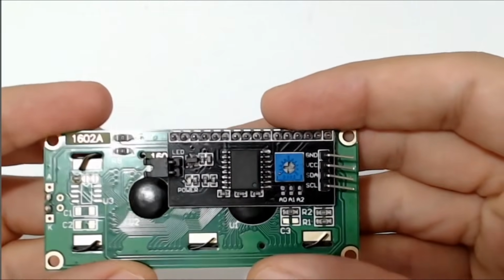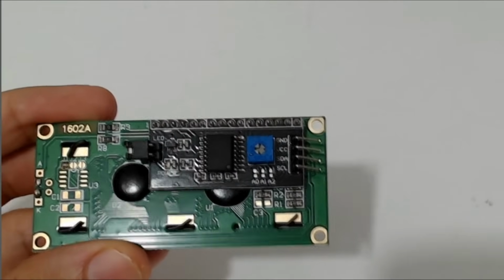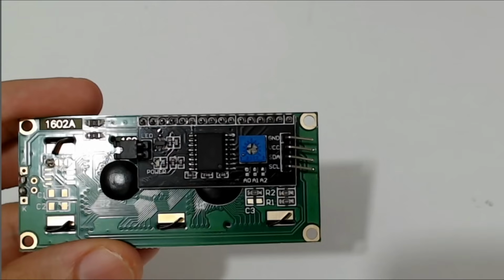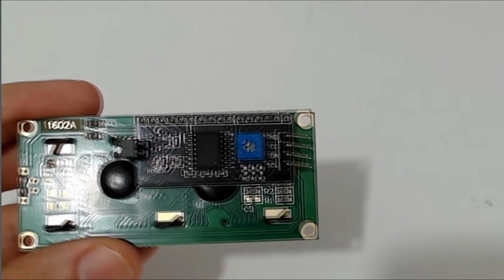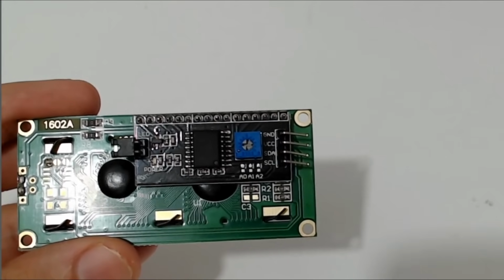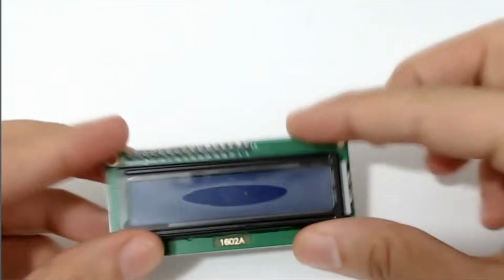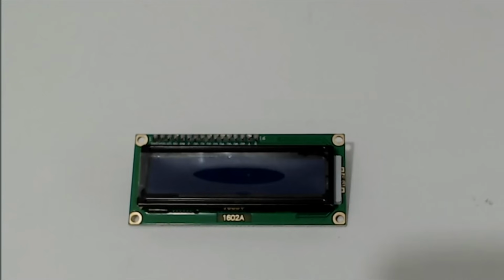2 of these lines are power lines, that is the GND and 5V pins. The other 2 lines are the I2C lines, the signal pins. Normally, we have to do a lot of wiring, but thanks to the I2C module, this wiring is considerably reduced. The SDA pin allows us to transfer data, and SCL is the clock. So the SCL pin allows us to transfer all data synchronously. Yes, my dear friend, we have entered our LCD screen section with a short introduction. So now let's move on to our other lessons and control our LCD screen with Arduino well.